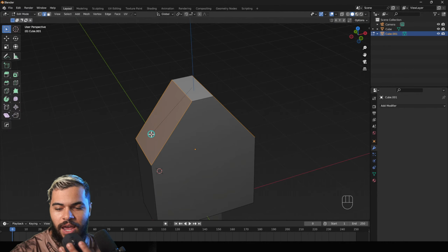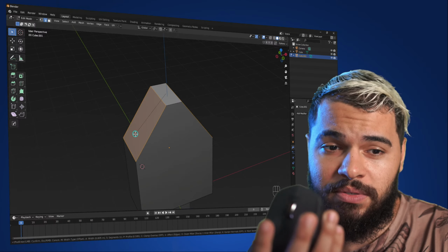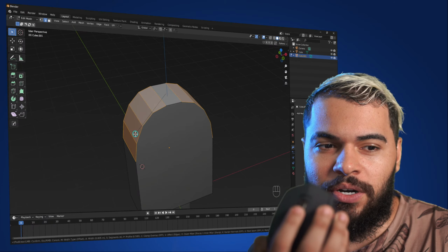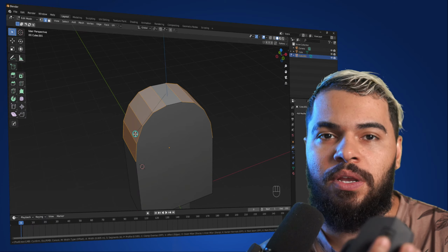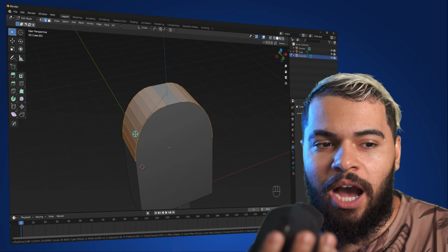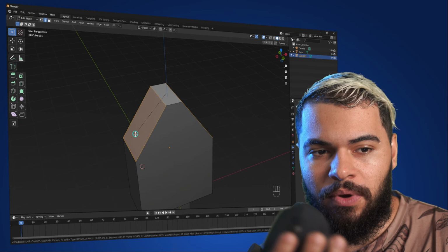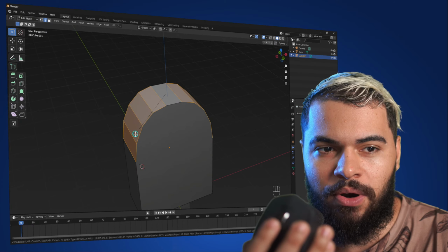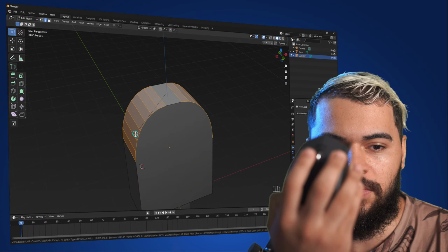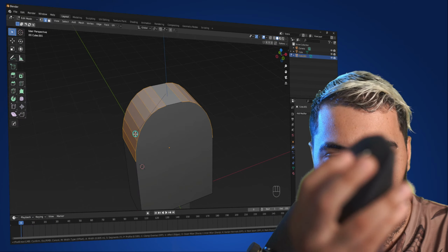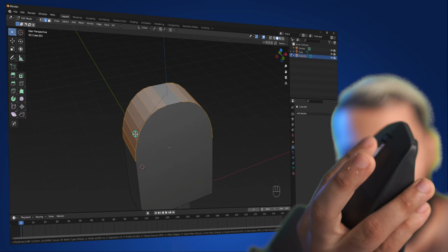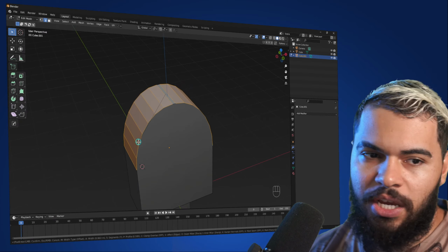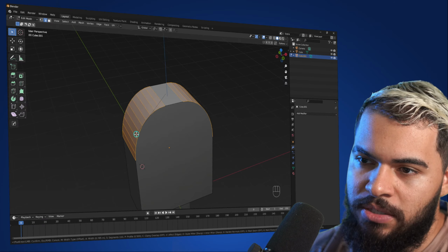But now, look at this, using your mouse, I'm using the mouse. If you scroll up, you can add more face polygons and make this high poly. Here we have low poly, one face in low poly, and you start to add more and more and more polygons. Simple like that. Using the mouse, my friend, look at this, scrolling. Where is the focus of my camera? Here, I'll focus. You see? Scroll that up, and then I can change here just like that. It's fantastic.